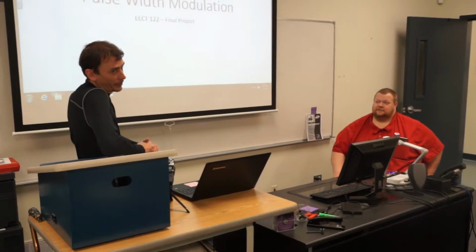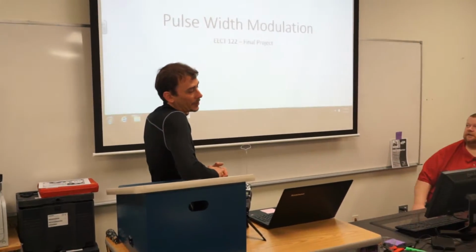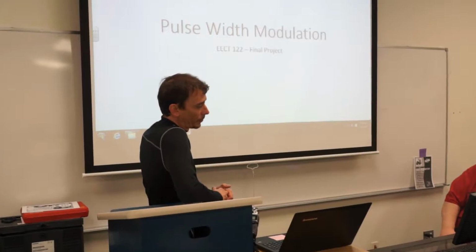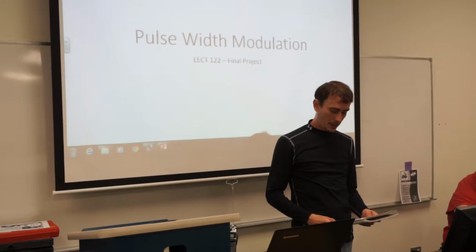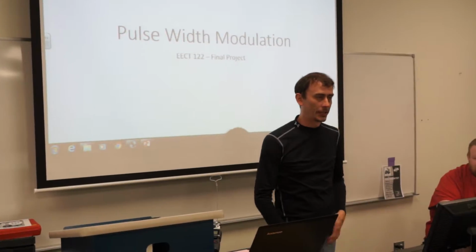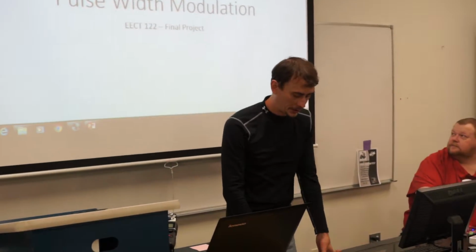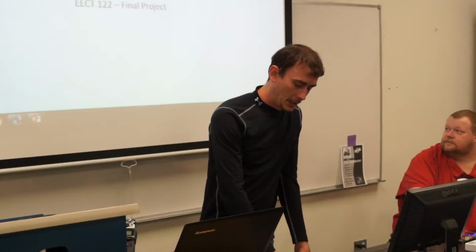group? A digital analog converter. A simpler, more basic form of DAC that implements pulse width modulation, PWM, which is a nice, cheap, affordable way of using a digital input to get a nice, steady DC analog output out of the other end of it. So I figured that would be the project we'd want to try to do.